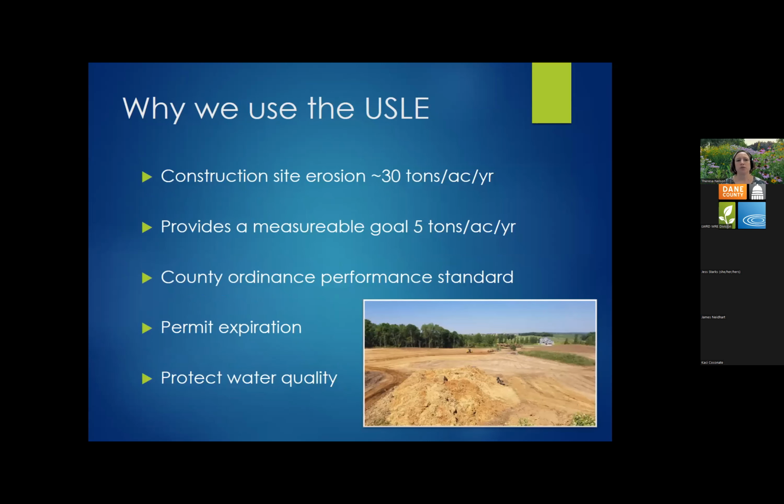So why do we use the USLE? Research shows that construction sites on average can contribute approximately 30 tons per acre per year of sediment to local waterways. Obviously this can negatively impact aquatic plants and animals. Using this calculation, we can get at a numeric goal for reducing sediment discharge from construction sites.